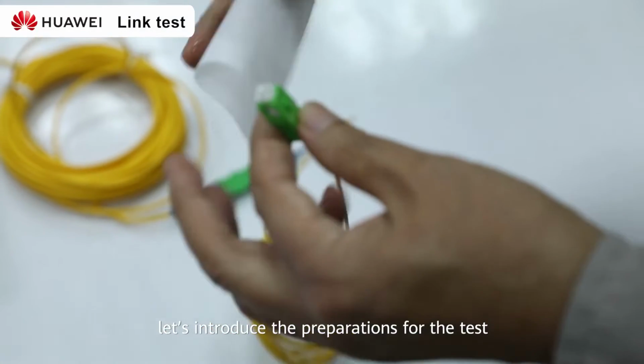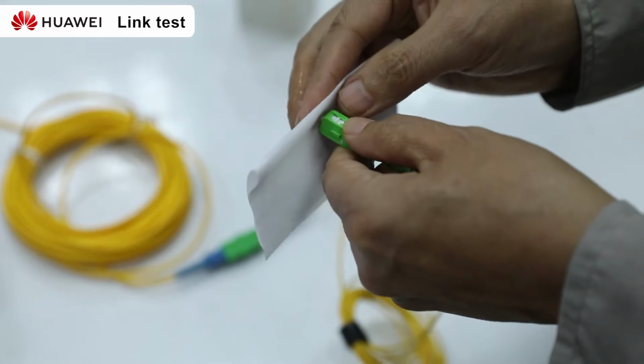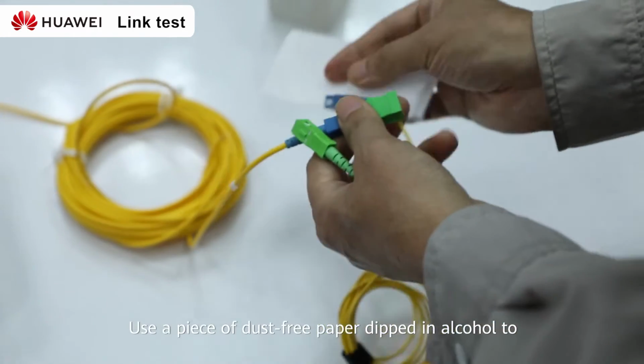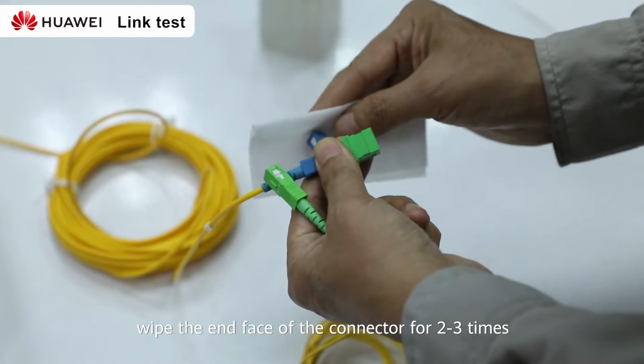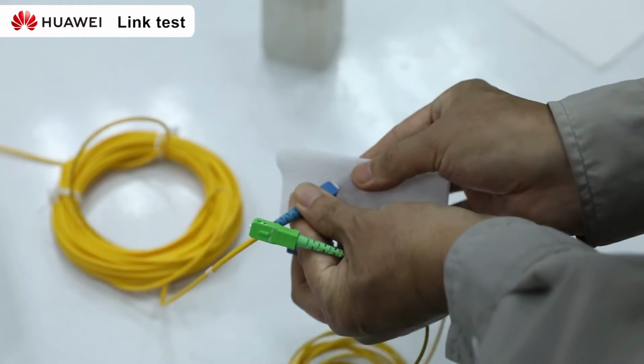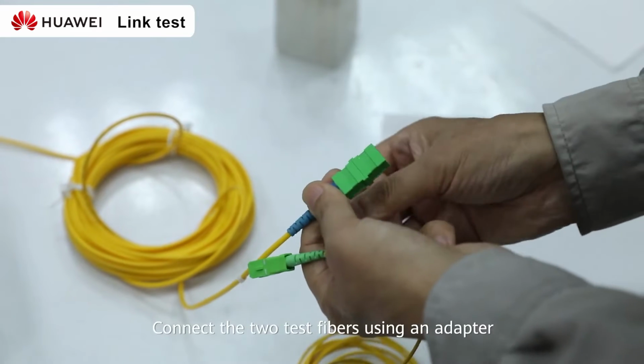Now let's introduce the preparations for the test. Clean the end surface of the test fiber. Use a piece of dust-free paper dipped in alcohol to wipe the end of the connector 2 to 3 times. Connect the 2 test fibers using an adapter.